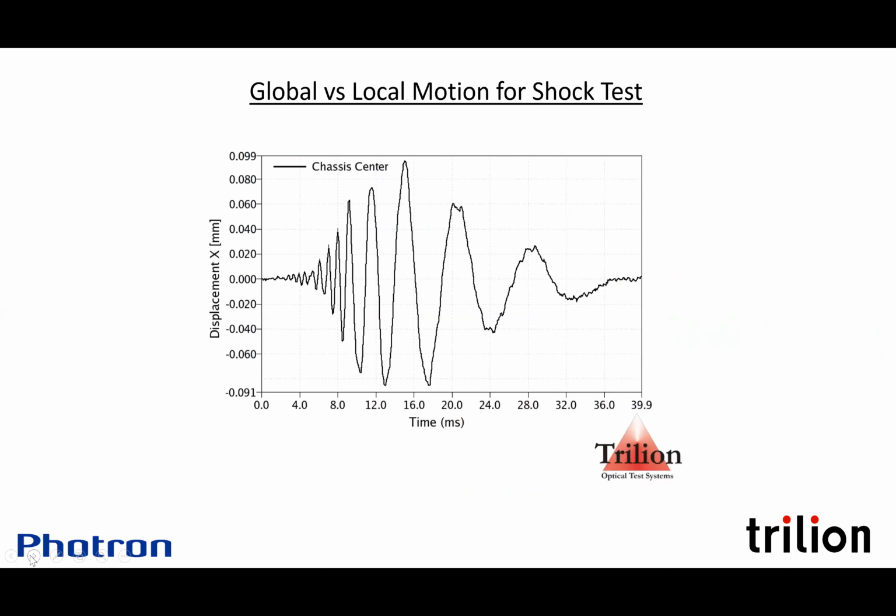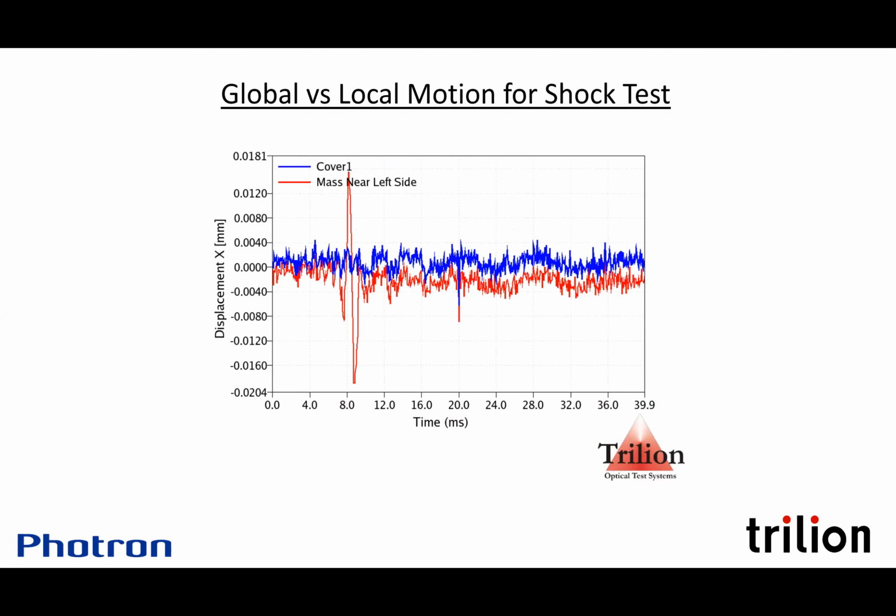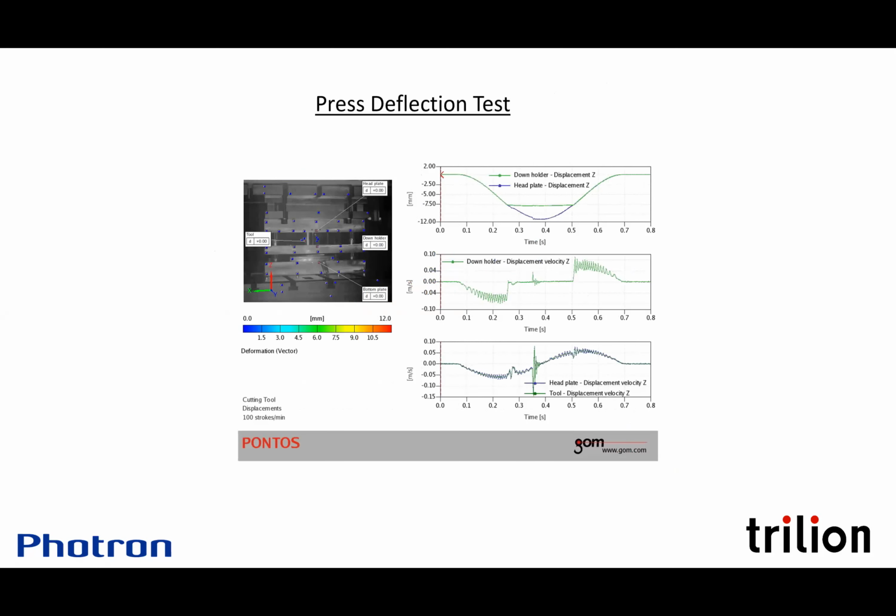Very convenient to use. This is the complete shock event. So with rigid body, we're basically quantifying the shock, checking that the shock is behaving as expected. Then we can wipe away the shock and be left with just the relative motion at much lower amplitude. So we were picking out 18 to 20 micron differential motions during that shock table test using the Mini cams.